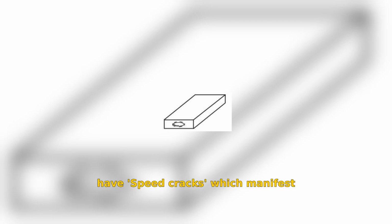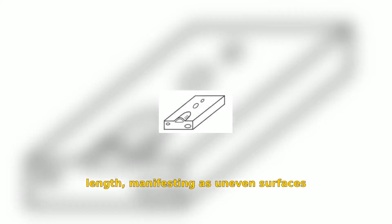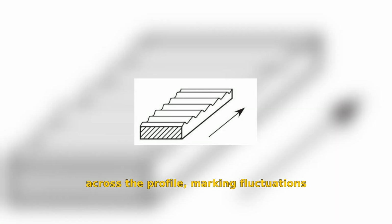Moving on, we have speed cracks, which manifest as transverse surface cracks and can even resemble a fir tree in severe cases, appearing mainly at high temperature zones. Next are blisters, which are air bubbles that may appear in lines or irregular patterns along the extrusion, sometimes referred to as blowholes once ruptured. Surface waviness can affect the strand length, manifesting as uneven surfaces across the profile, marking fluctuations in quality.